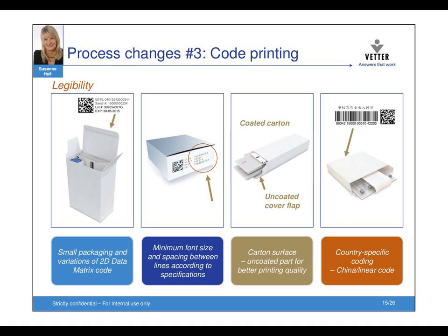Looking at the different packaging designs, we have different challenges. We need space for the printing of the variable data and the 2D matrix code. This area has to be varnish-free for some printing processes, like for an inkjet printer. After printing, a camera directly controls the information regarding correctness.